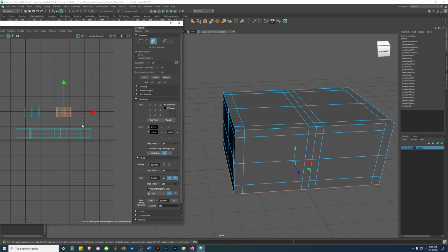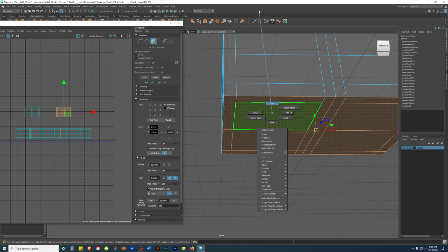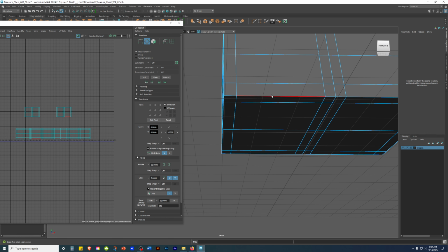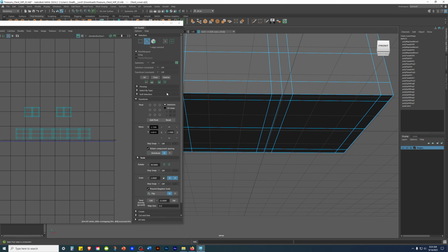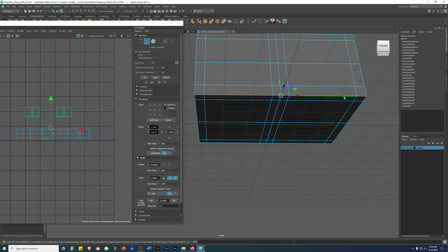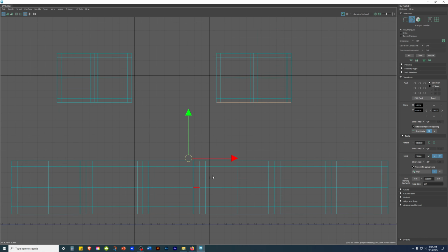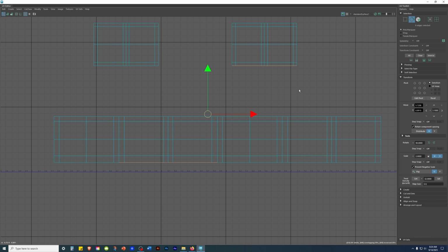Now I'm gonna just grab this. I'm gonna have this, right click, hold edge. Let's figure out, grab that one edge, hold shift, double tap. That way I know that seam. This is that. This is that. Right click, hold UV shell, grab that shell,